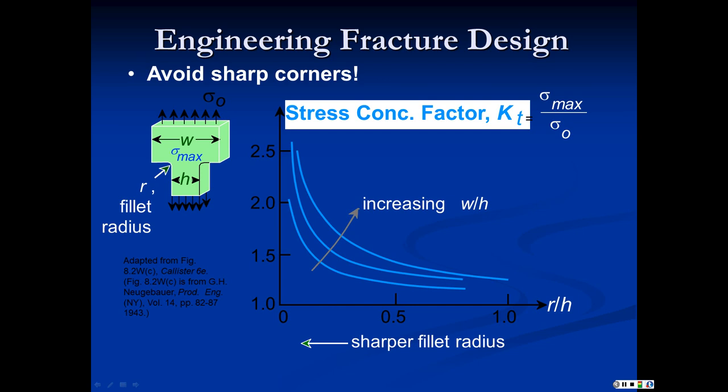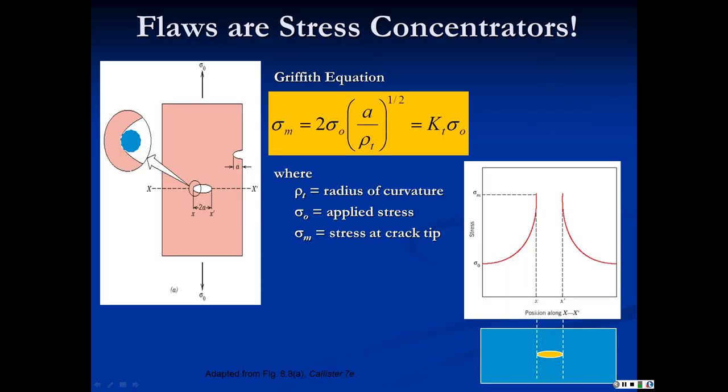And you have general solutions for preventing fracture or failure by stress concentrations, and things that you will apply in mechanics of solids and in machine design and in structural analysis, where you have tables that allow you to calculate a stress concentration factor, KT, for a given geometry. And so if you go back to the Griffith flaw, A over rho, the square root of all of that, times 2 is a stress concentration factor. That is, it's a single number that you can calculate, that you multiply by the far field stress to get the local peak.